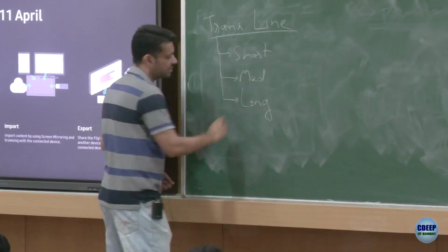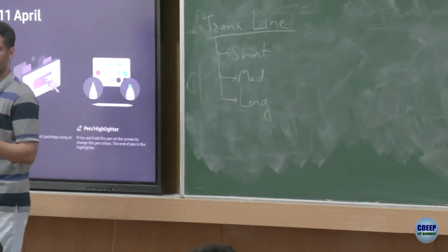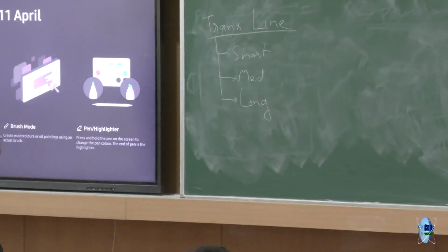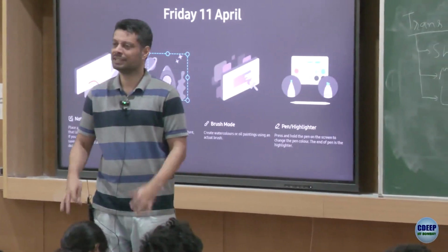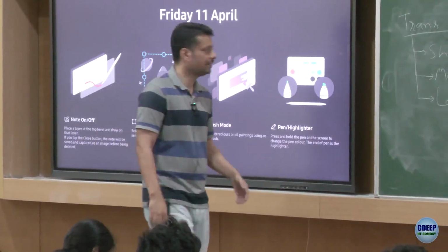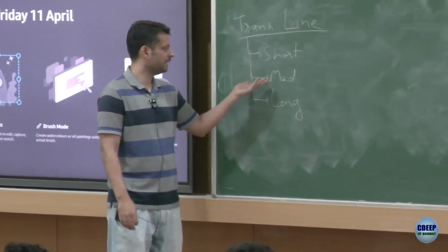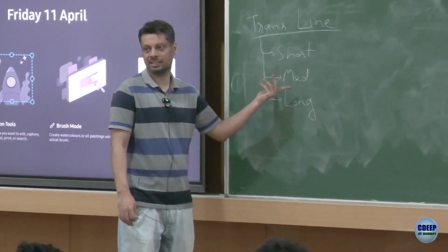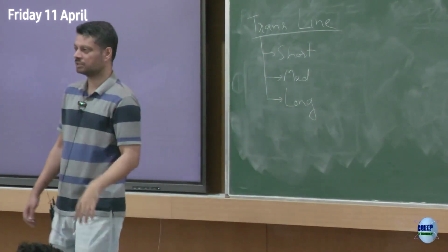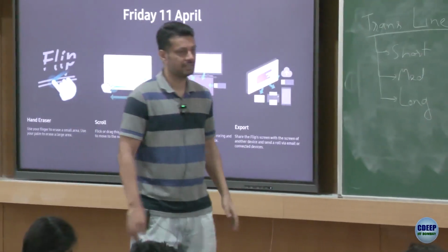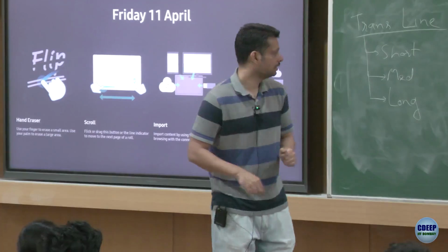Now if you ask me honestly, what do you mean by short? 1 kilometer, 2 kilometer, 5 kilometer, 10 kilometer. Of course, in books and references, if you Google, you will get some sort of boundaries, but these are all very flexible boundaries. So usually short may be about 50, 100 kilometers, medium maybe about 100, 200, 300, 400, 500 kilometers. Anything beyond that would probably be long. So these are all rough boundaries. There is no hard and fast cutoff there.